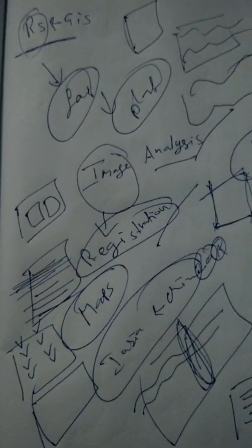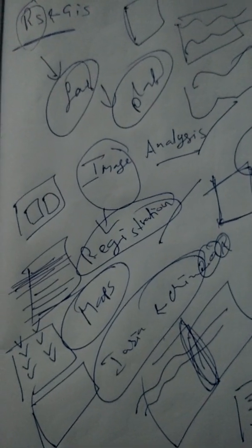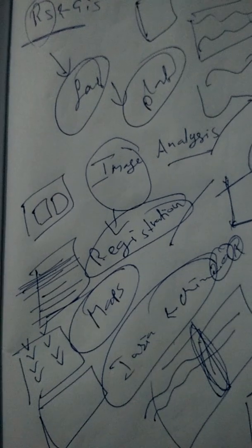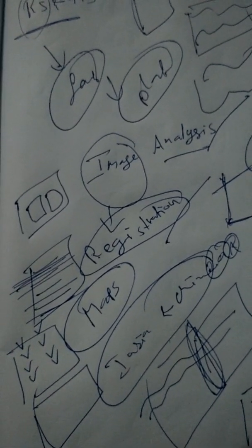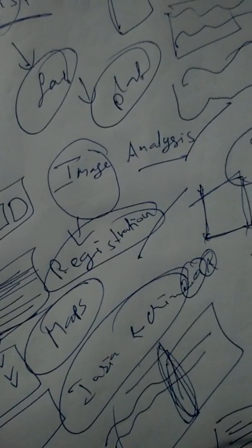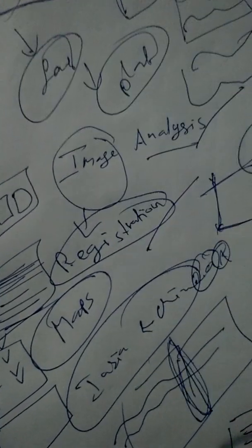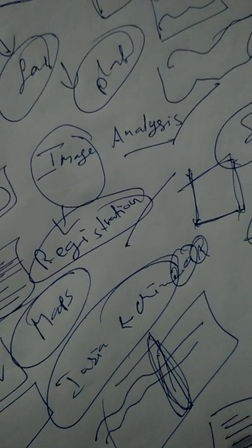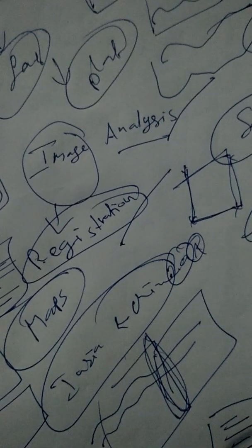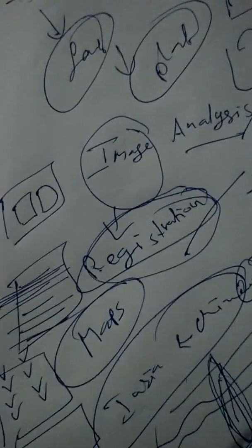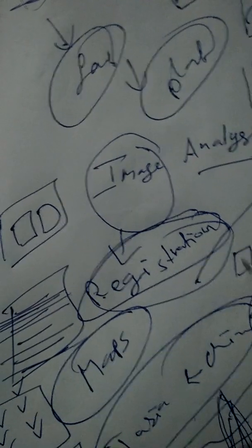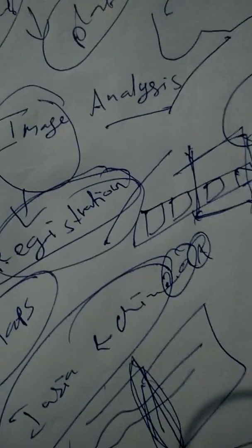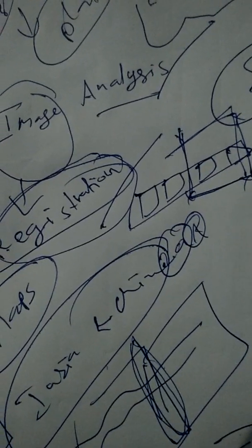The process of alignment of translation and rotation is carried out by positioning two images or maps of the same geometrical set of objects with reference to one another, obtaining corresponding elements or registered images. Image registration is the most precise geometrical correction, where each pixel is known not only by its row or column in the digital image matrix, but also by degrees, feet, meters, or standard map projection. So here it is explaining that registration is not an easy thing. If you take the pictures alternately, 1, 2, 3, 4 like that, you must be able to set them in order, in alignment, so the objects in the pictures are aligned.